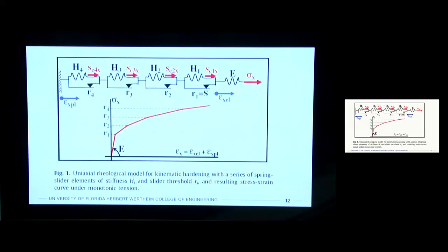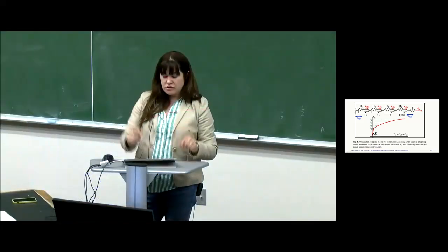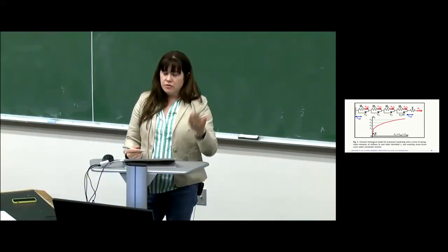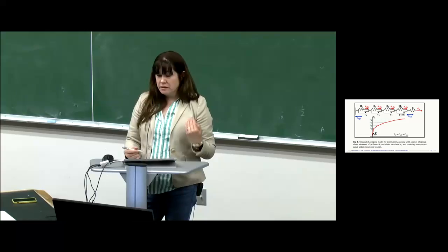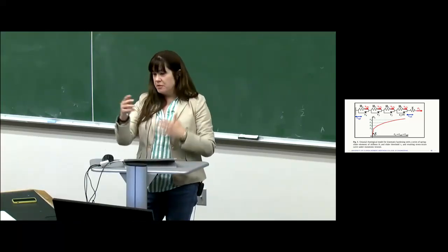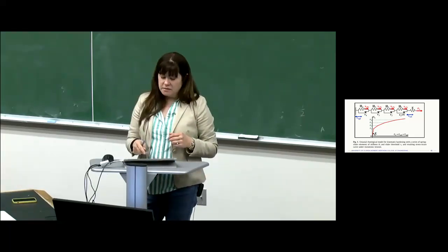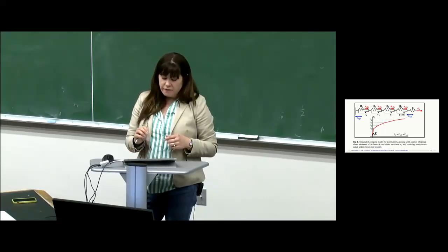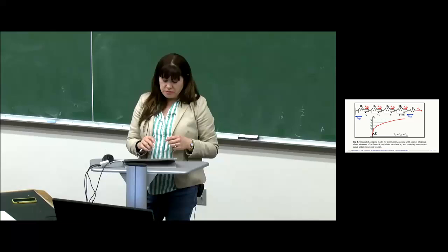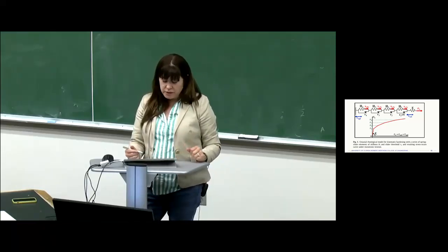So this is one way that they give sort of a schematic to describe what they're talking about when they talk about these infinitesimally small changes in stress or strain that they are integrating, right? And so if you think back to what you know about springs, or maybe your vibrations class, where you have springs and dampers and all sorts of series and parallels, right? We can even apply that system to the damage state for fatigue damage. And so this figure says uniaxial rheological model.